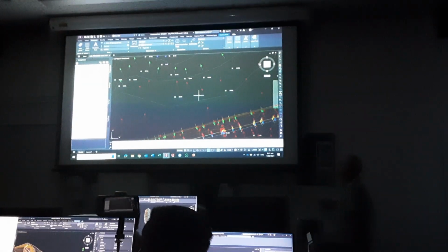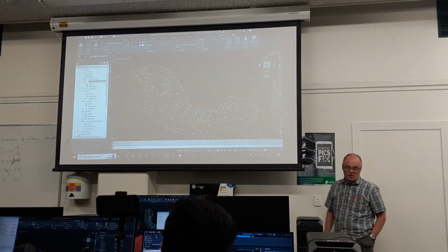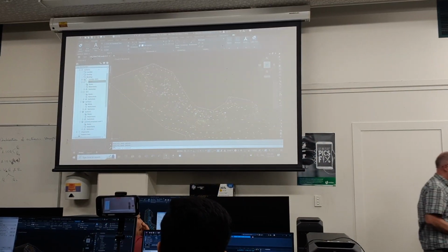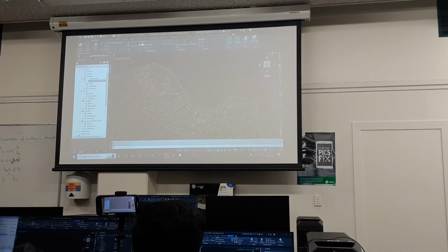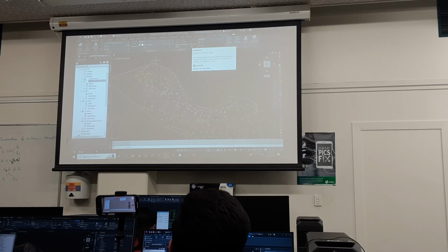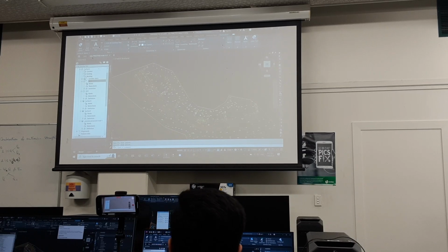And now that I've successfully labelled all my contours, once again, you need to work out your text type. I just made that 0.3. You may need to make that a bigger text type or a smaller one, depending. Just rolling down now, you can see that that's me drawing the line, and each one of those is the contour appearing. Okay, so time to do another save as.